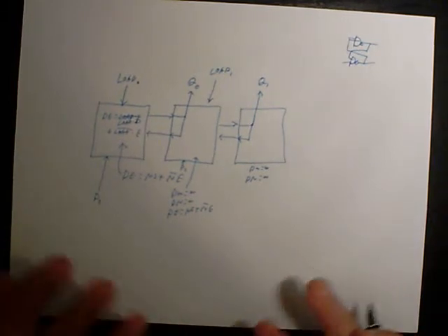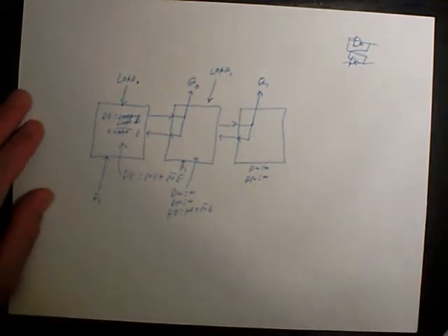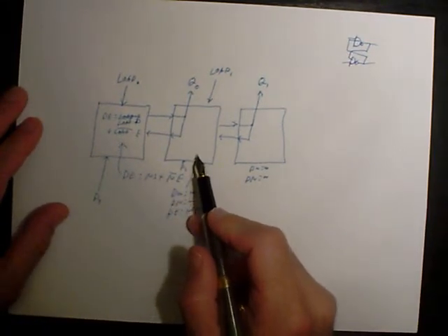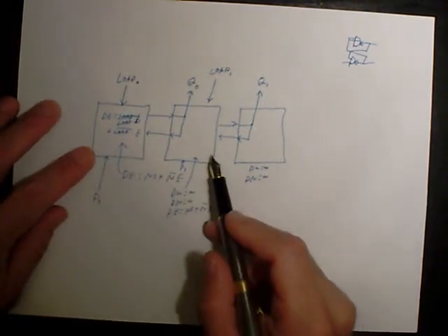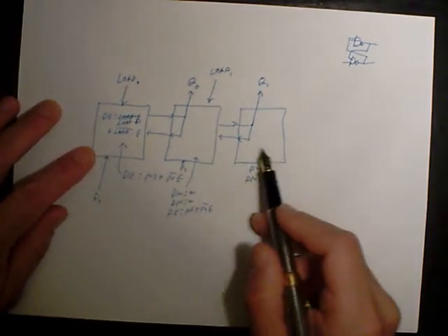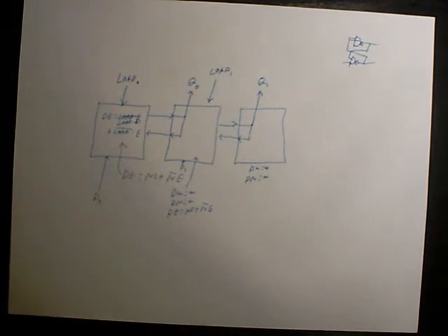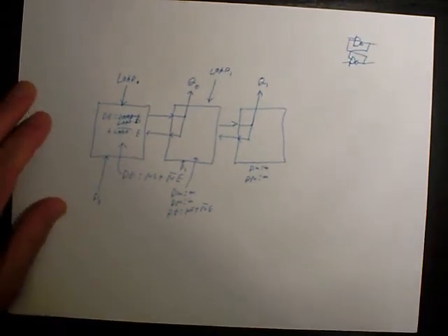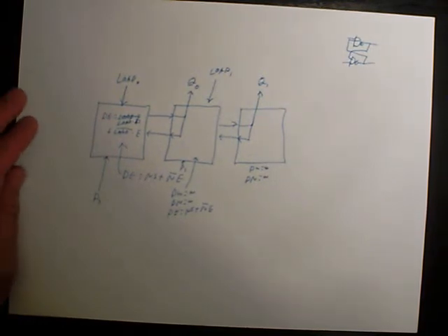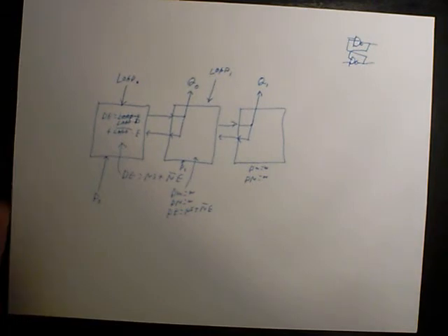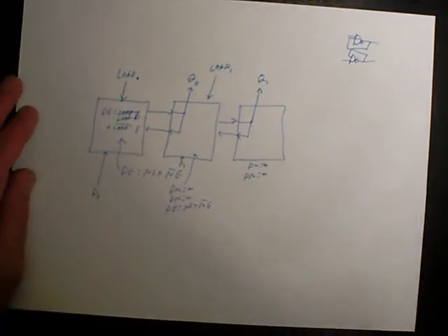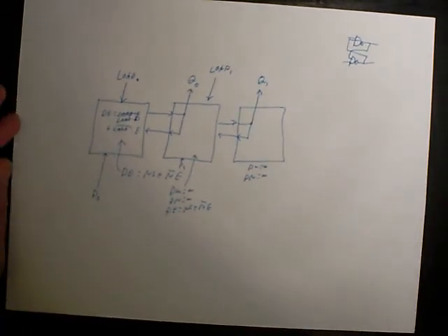So this is an example where we can take these cells and we can use them for multiple purposes. This cell is both the refresh part of this latch and also the input control part of this latch. So we can usually do better than just starting with a straight digital circuit using simple logic gates and implementing that directly on cells. You usually get a better implementation if you think of these cells as being more powerful blocks and you work from that point of view.